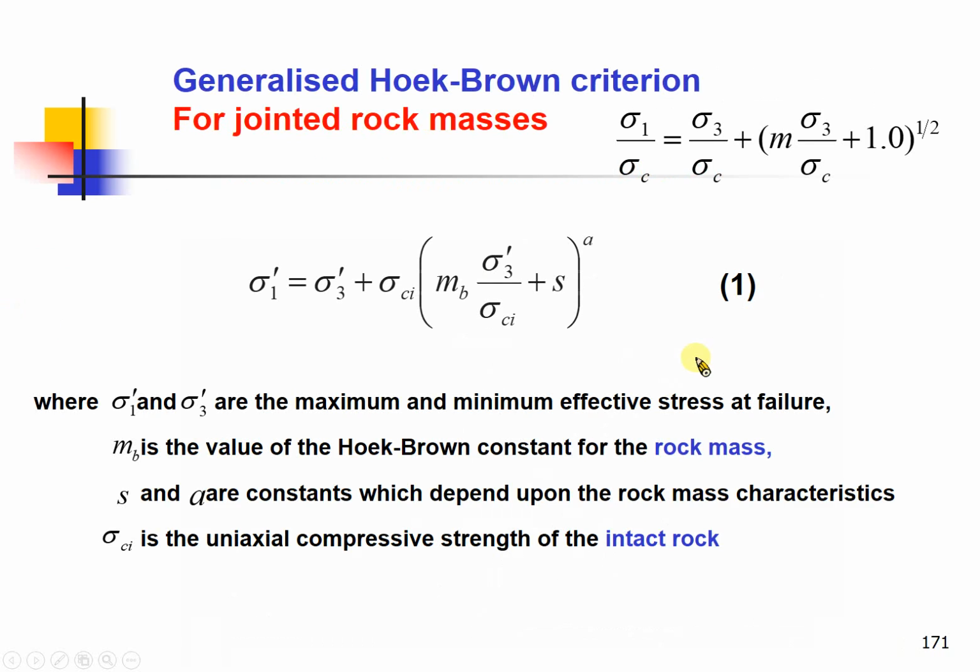And this value is determined by the rock mass structure on the vertical axis and the discontinuity condition on the horizontal axis. From the best, 100, to the worst, 0, you can determine the GSI. So mb and s will be functions of GSI.